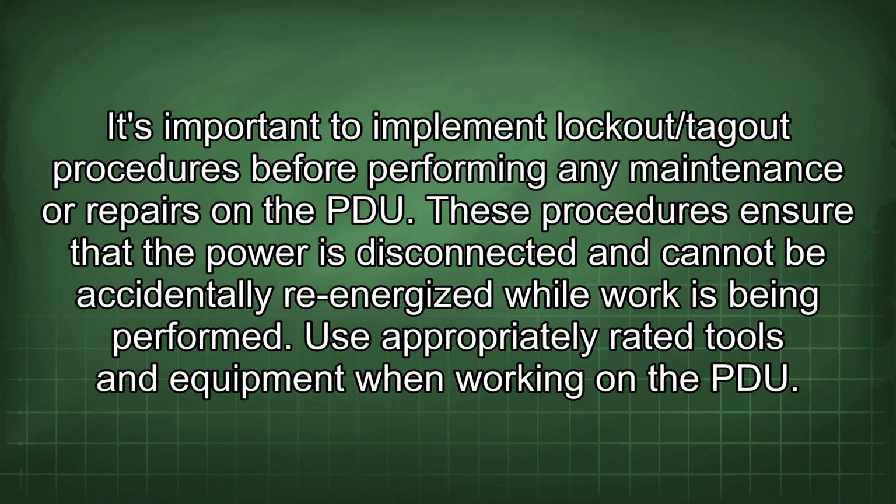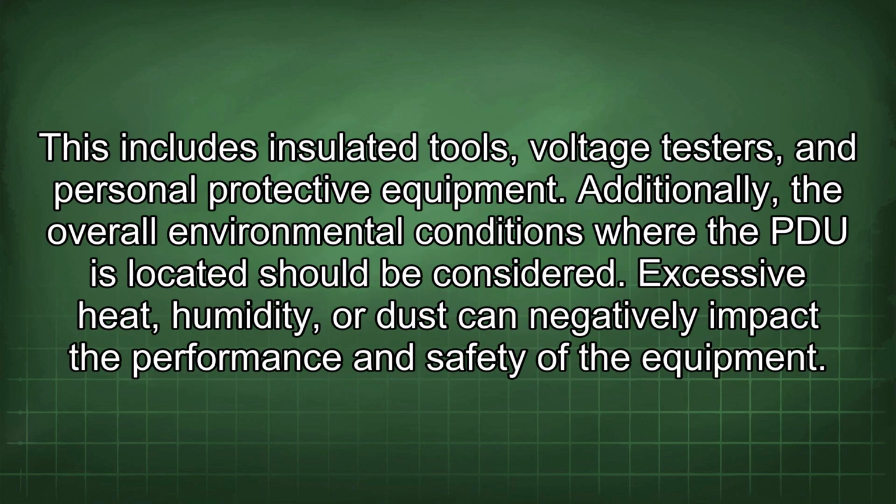It's important to implement lockout/tagout procedures before performing any maintenance or repairs on the PDU. These procedures ensure that the power is disconnected and cannot be accidentally re-energized while work is being performed. Use appropriately rated tools and equipment when working on the PDU. This includes insulated tools, voltage testers, and personal protective equipment.